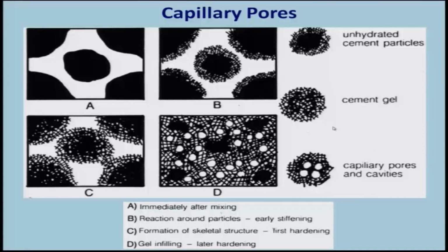In Portland cement based paste systems, the hydrated region is generally referred to as cement gel, and this cement gel primarily contains the major hydration compounds like calcium silicate hydrate gel, calcium hydroxide, AFt ettringite and AFm monosulfoaluminates, all clubbed together and called cement gel.